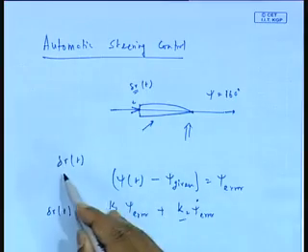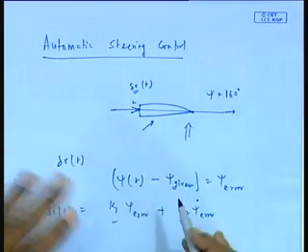Now, if you go to a boat builder, he is continuously correcting this rudder by hand, like you would be continuously correcting in a cycle, trying to maintain a direction. But nowadays the concept is more of an auto controller. You automatically set the controller so that it automatically keeps on correcting. In fact, I have seen myself on a ship, the rudder continuously turns a small amount. But the question is that I must have a signal to the rudder for how much it should turn to correct the error. Obviously, I have to correct the error, so I have to turn it. And so this turn should be proportional to the error. That is one thing.